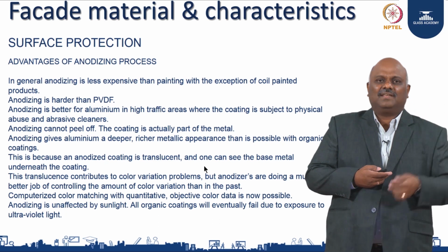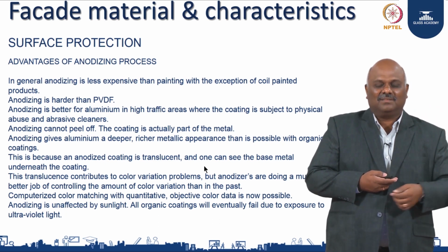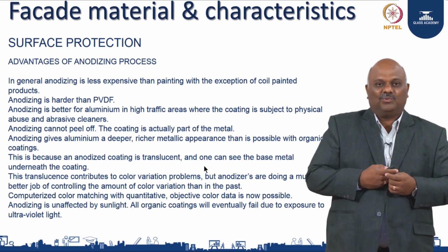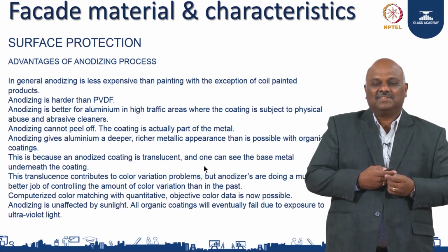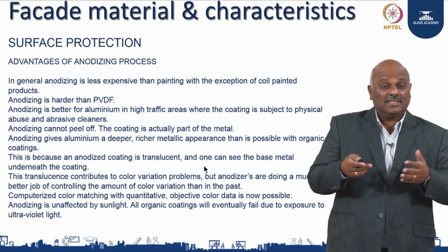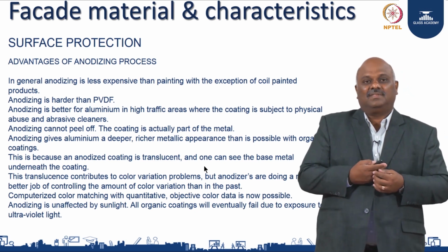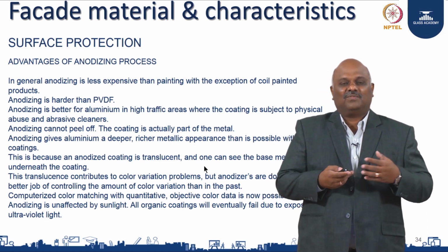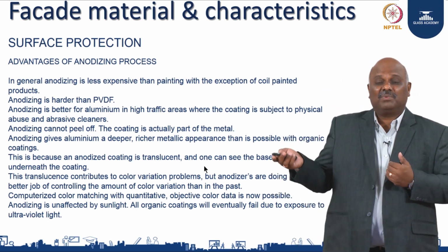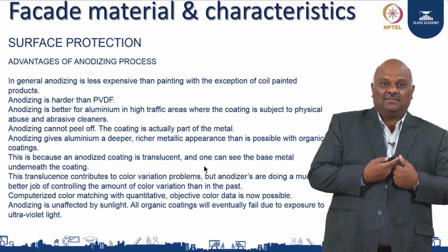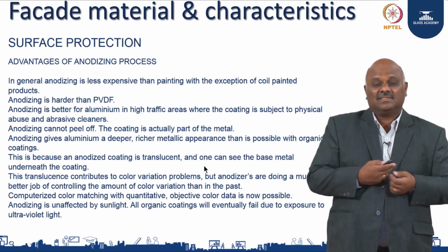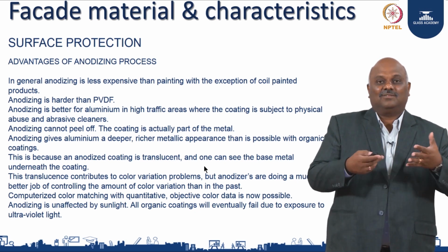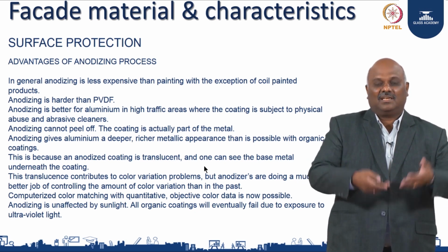And you get a variety of colors. You can do a million colors with PVDF. So, there are pros and cons and advanced systems. At the same time, when choosing the coating system, you have to be very careful about what surface protection I am going to give. Why? It is not for funfair. For example, I don't want to put PVDF on the internal of the building. It's not only expensive, but it doesn't help. Why should I spend so much money on PVDF? Rather, I do some other coating like a powder coating.